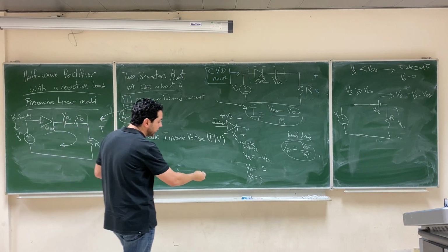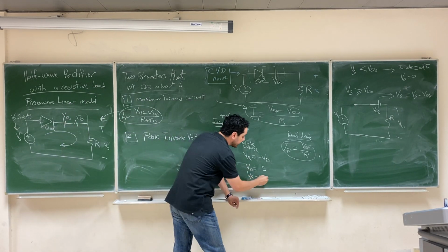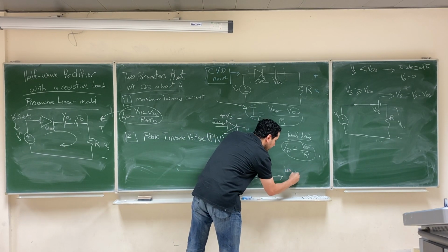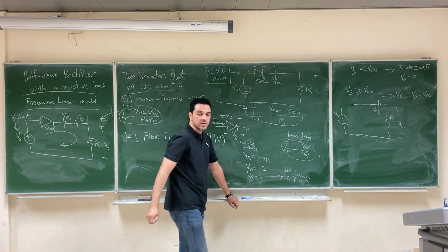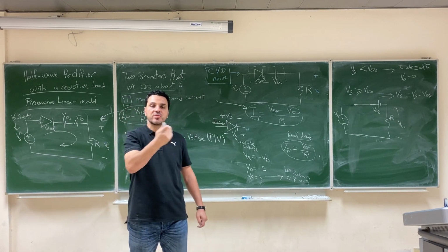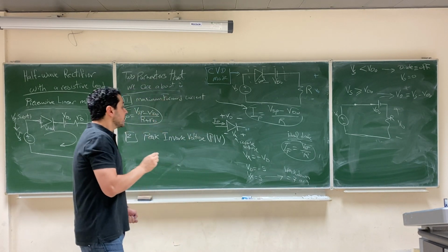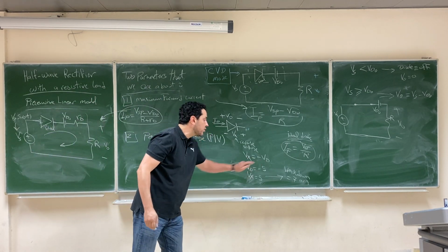So for example, if you find that the peak inverse voltage that will affect your diode is 5, then you have to buy a diode that has a breakdown at 7 or 9 reverse voltage. 7 or 9 reverse voltage means -7 or -9 diode voltage, right? As I explained here, the reverse voltage is the negative of the diode voltage.